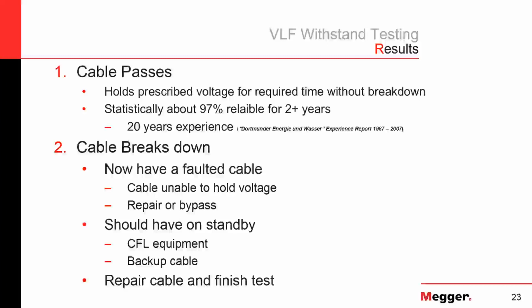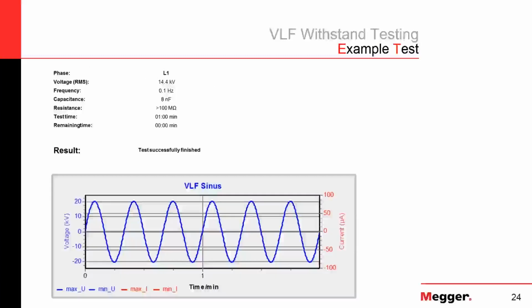If the cable does fail, we go out, repair the cable, and continue the test. We don't need to restart the test. If the cable failed at 15 minutes in, we go and repair the cable, we start the test back up, and we hold the voltage on there for 45 more minutes. We don't need to restart from 0.